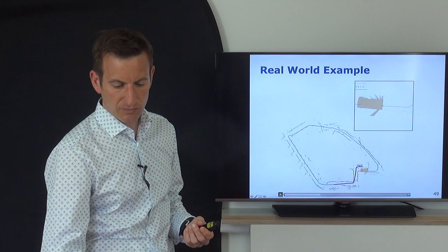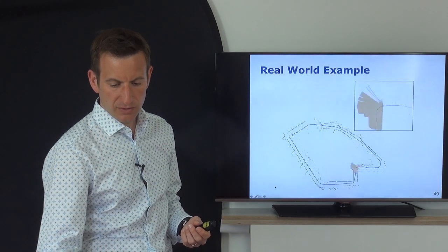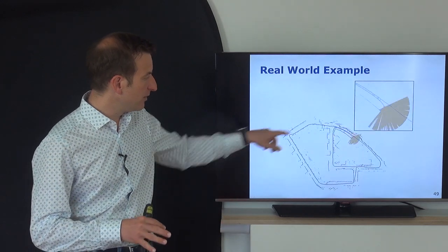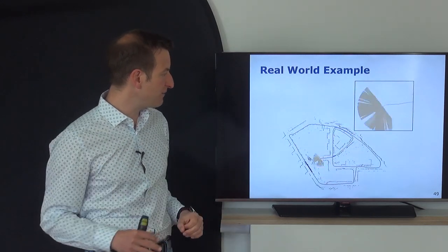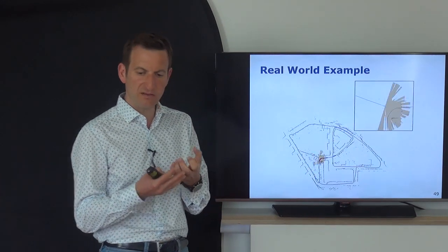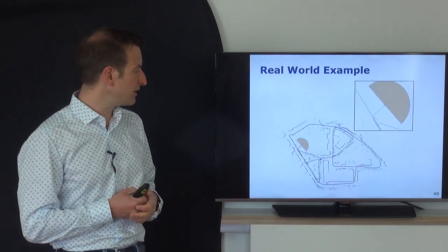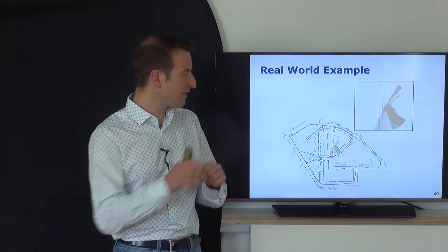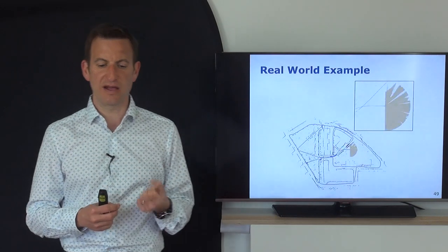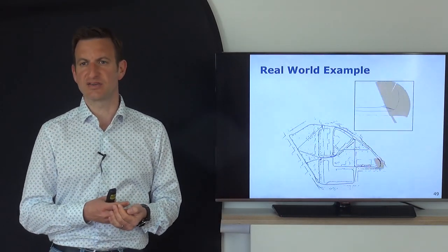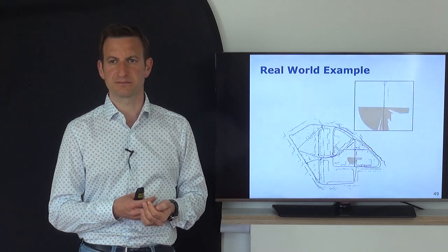If I restart and rerun the video, you saw it shaking a little bit. It will happen again now when the robot re-enters the map. You see the map shaking a little bit. The more loop closures it has, the smaller this effect is, because the corrections have already been taken out. But whenever this happens, you see small corrections and the map is realigned. This is the visible result of the least squares approach that is running behind that.